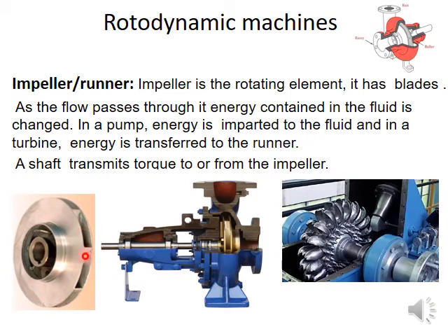The small pumps that you have at home, like domestic water pumps, usually have this type of impellers. So you can see there are blades. This is a covered impeller. There is a plate this side and that side. Inside you can see blades. We call them blades or vanes. You can see the edge of those here and the beginning part is here. So fluid enters here, water enters here and leaves here with high energy, usually high pressure.